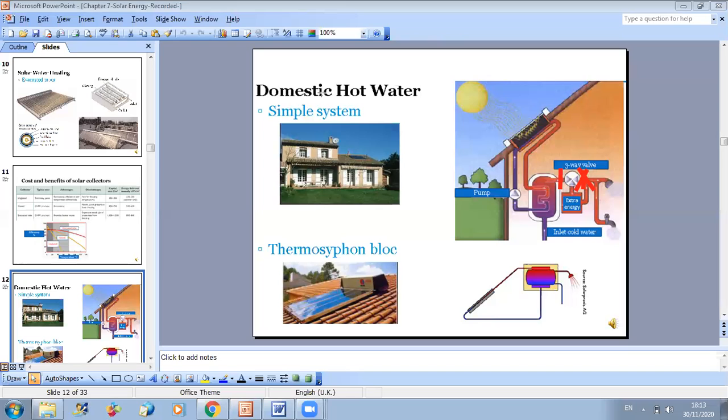Why do we open it? Because we can store hot water now. This valve will take water into a reservoir for extra energy, so we will store hot water in our reservoir. And then when it's needed, you can use it either from the reservoir or directly from the sun. The reservoir is very important because during the night you don't have solar energy, so you can benefit from the energy stored in your reservoir to supply hot water.